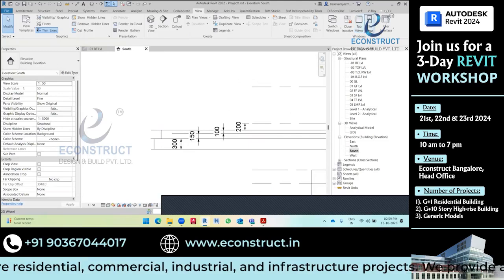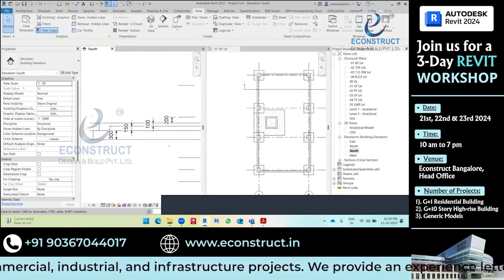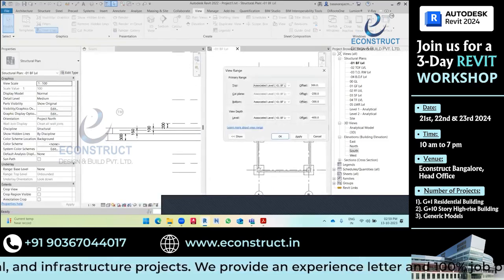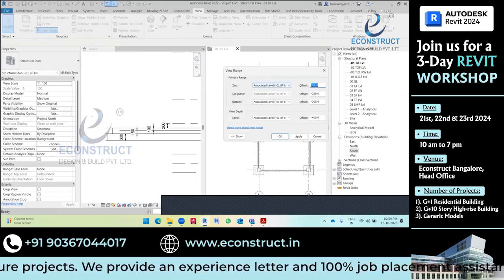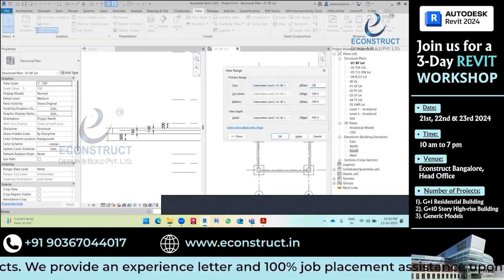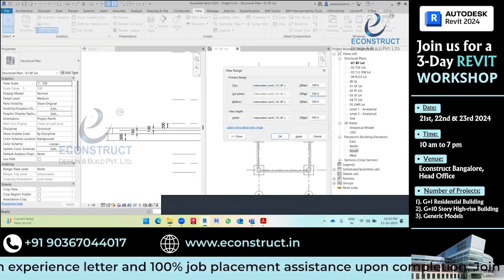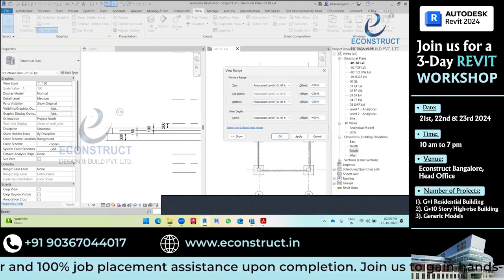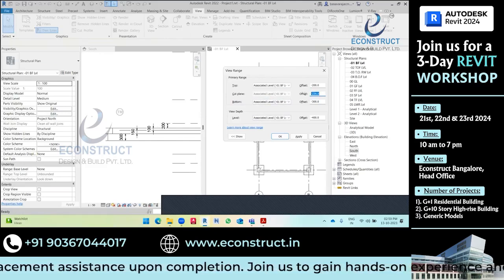Okay, now this view range I will set for this view. From the basement floor level, it is minus 200. And from the basement floor level, the cut plane is 200 plus 100, so minus 300.